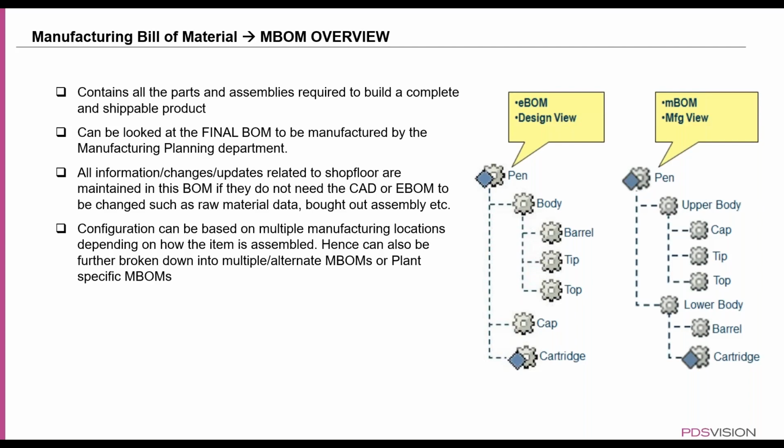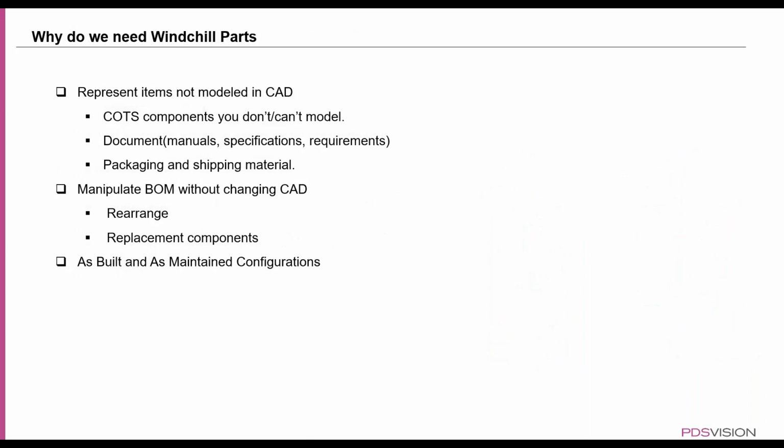And as I said, that MBOM is built directly from this EBOM, so there's a complete link to it. If something changes on the EBOM, it will be reflected on the MBOM to show that there's a change, and you can decide based on the change if you want to pull it into your MBOM or not. So there are those two important structures that you can create. And the nice thing that I didn't mention is that someone on the MBOM side can manipulate and modify that structure without worrying about affecting the EBOM side of it.